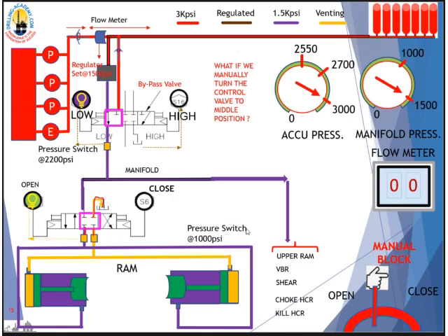You don't do it in drilling operation. You only do it when you are in a rig move or you are maintaining, servicing your BOP. When you service your BOP, you open all the BOP functions and you place the control valve at the middle block position.